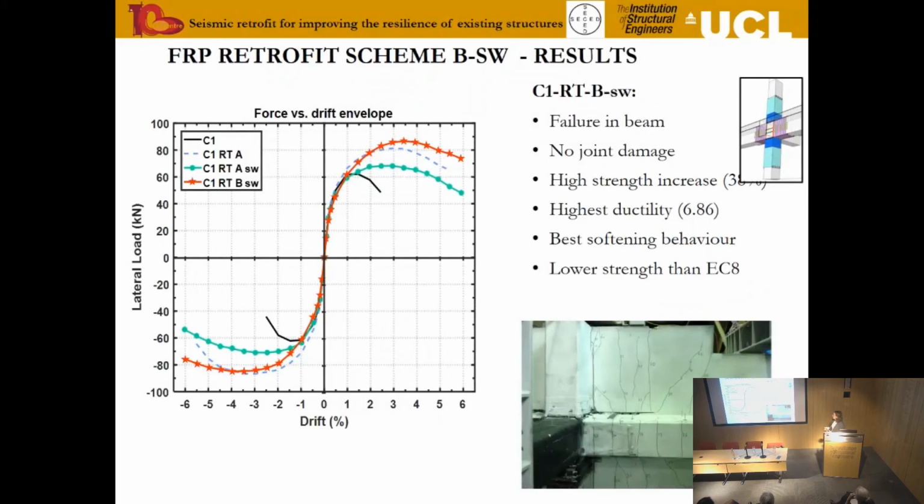So, what did we achieve? Well, the latest strengthening approach did achieve a much higher strength than just combining the two columns. It achieved the same level of ductility as we saw by cutting into the slab. Of course, it's a combination of the two, and it's almost a perfect combination of the two, strangely enough.